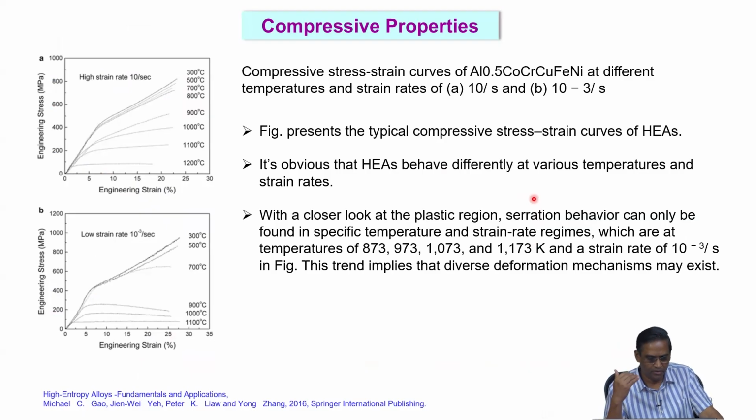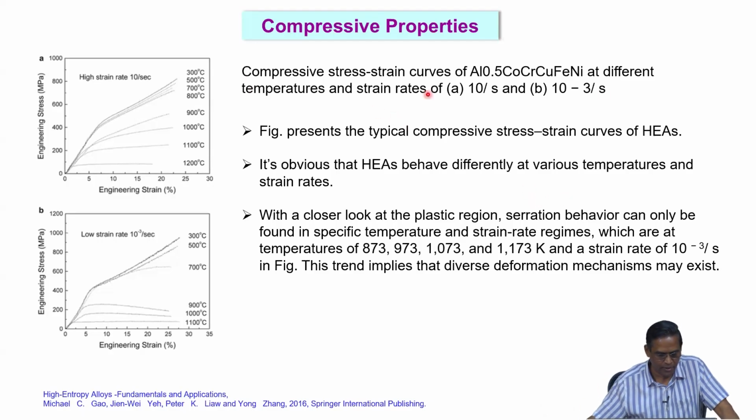Then people looked immediately at hardness, and they wanted to study the strength. Usually we do strength measurements by the tensile test. That's a standard test. But in this particular case, people started doing only compressive tests because the volume of the material synthesized was too small to fabricate a tensile sample. A compression test can be done just by making a small cylinder and compressing it between 2 plate ends, and then measuring the strength and elongation.